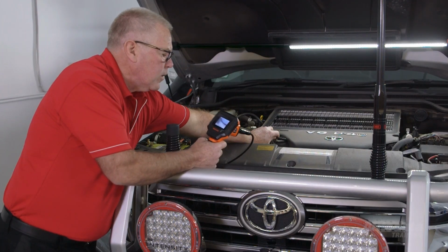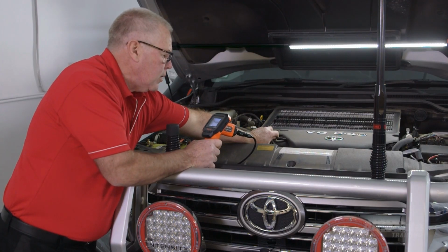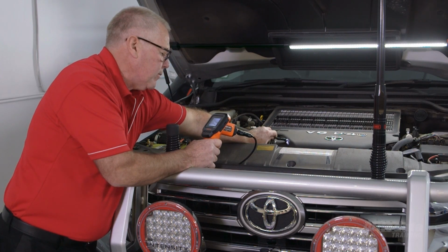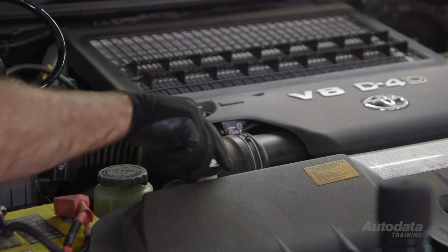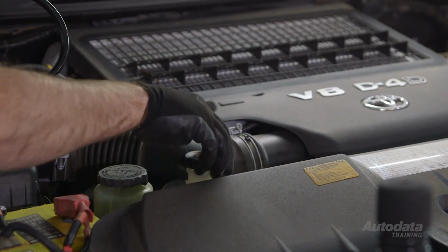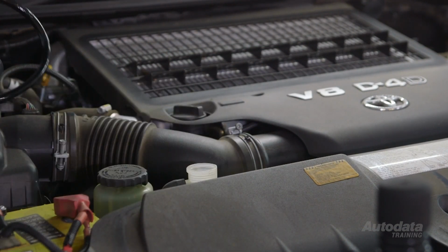The intake systems are complex these days. Make sure they are not restricted due to EGR issues and have no signs of oil. And don't overlook the cooling system. Remember, cooling temperature will influence exhaust temperature.